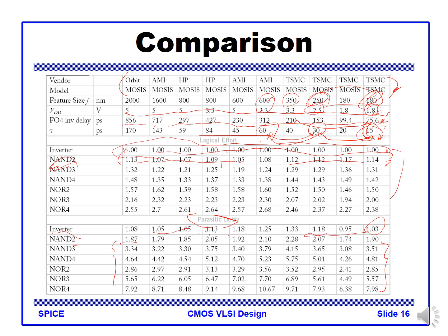This is something that we can see the trend here, right? Definitely NOR compared to NAND is a lot worse than NAND 2. So when you design a logic block, you just use inverter and NAND 2. That's kind of a way to design the faster building block.